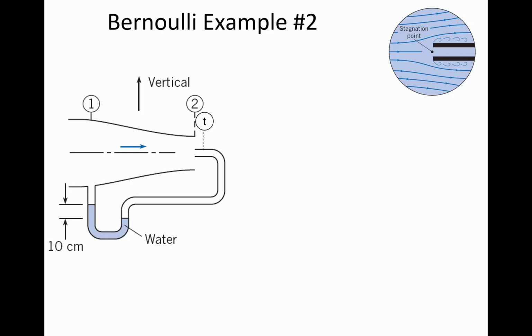What you can see from this manometer, because there's a deflection of 10 centimeters, is that the pressure is bigger on this side than at this opening. So there's more pressure here than there, and that pressure continues through as a gas, and it pushes down on the right side of the U-tube manometer harder than the pressure is pushing on the left side. And so since the pressure is higher over on the right, it deflects the water upward on the left.